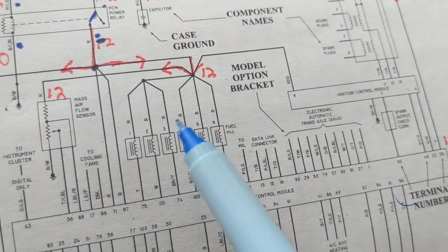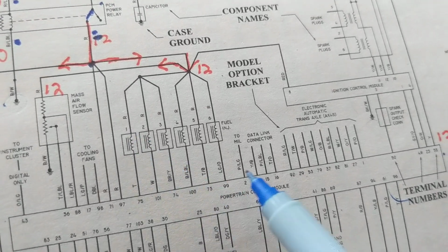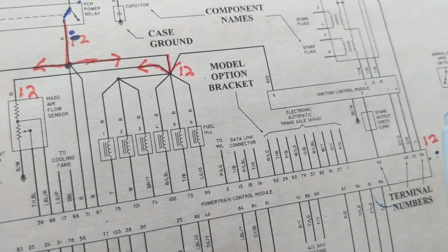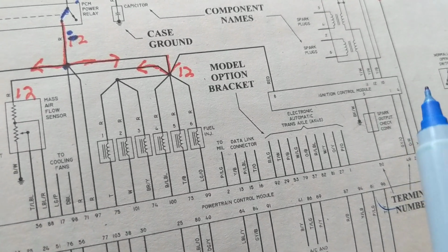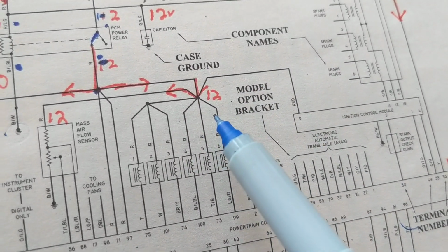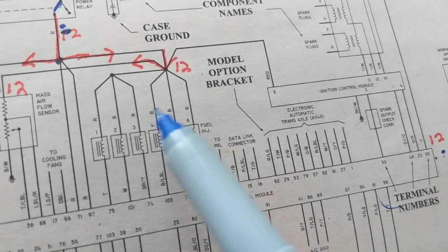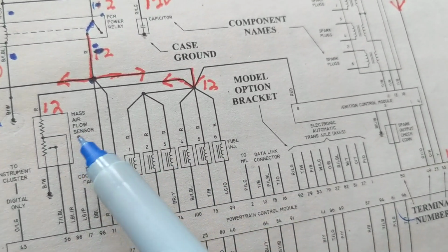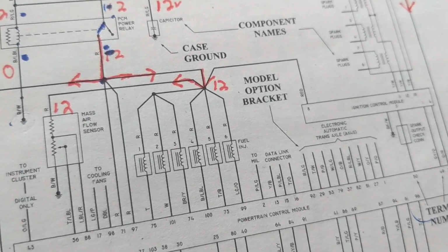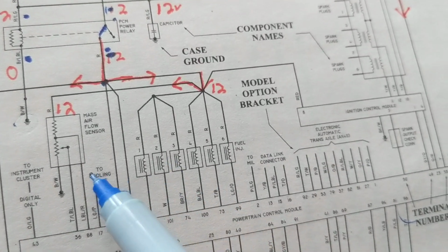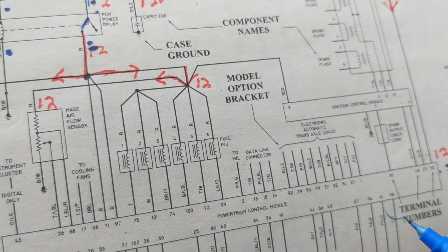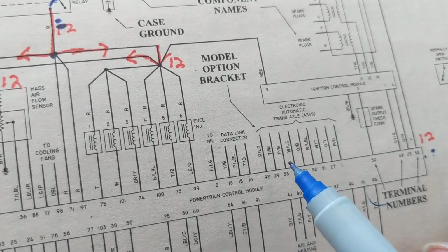The computer looks at 100th of a volt to determine the correct information and data, which are programmed and stored in memory and a microprocessor, and then it uses that information to increase or decrease fuel, where? In the fuel injectors. This has to be precise. That's why I always stress, unless you have a car that's, let's say, 300,000 miles and has many problems, why go to the dealer to spend so much money when you have so many problems with a car with so much mileage? That doesn't make sense either, right?